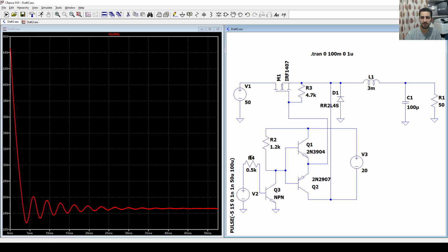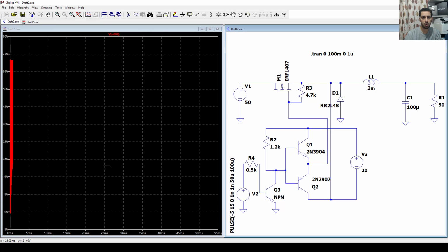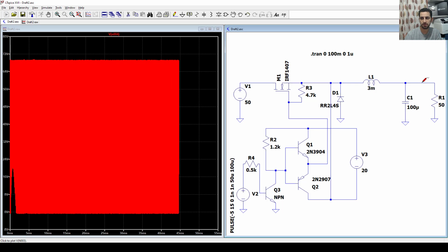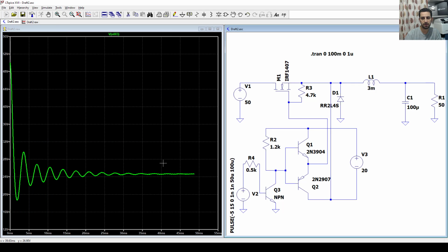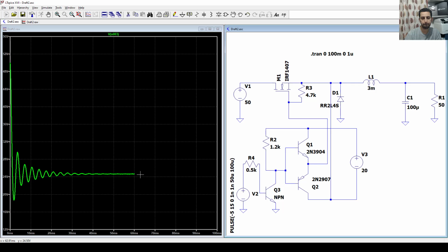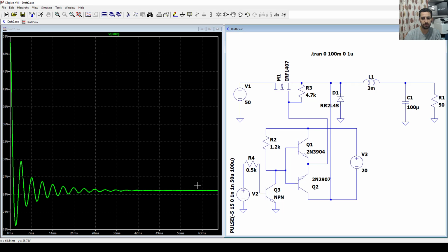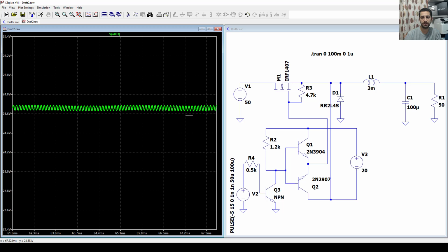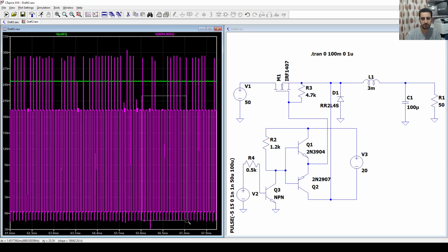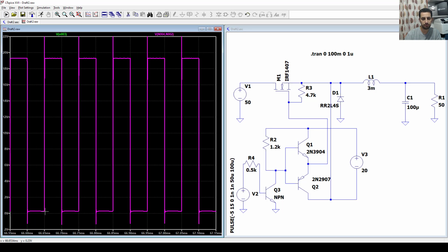So now all that circuit is between the source and the gate, and that voltage is between the source and the gate. So now if I run it, I will know if I'm driving it well or not by looking at the output. So now let's look at the output signal. Yeah, here's the output signal. Okay, and again it's going to 25. That means, yeah, we are driving our MOSFET in the correct way. So if I now sense the voltage to source, I think we are going to get some pulsation. Okay, and that pulsation is from 0 to about 20, which is the proper one.